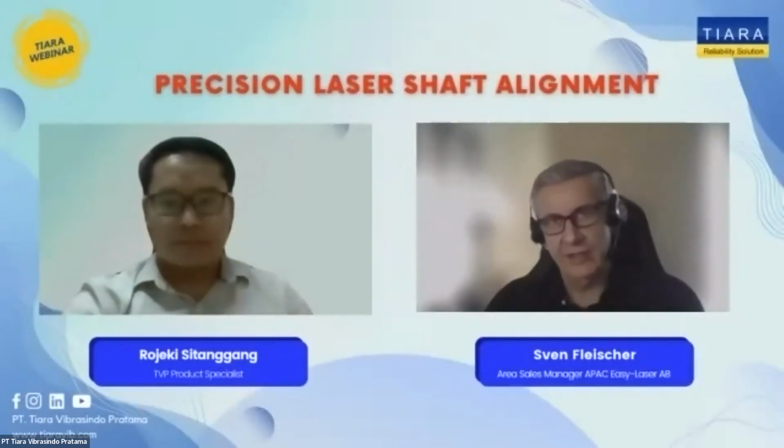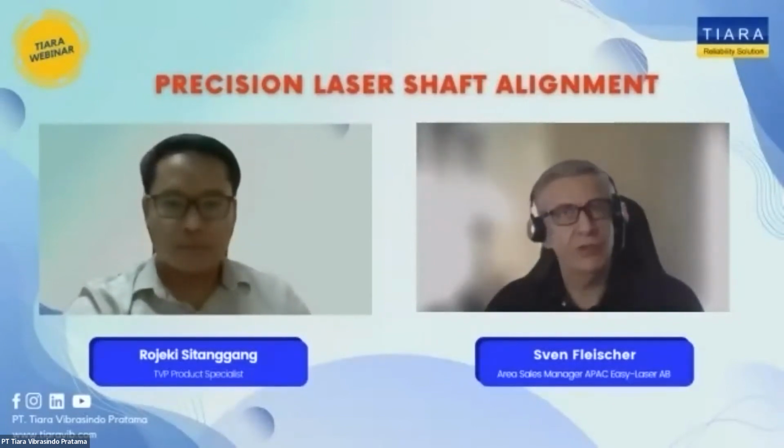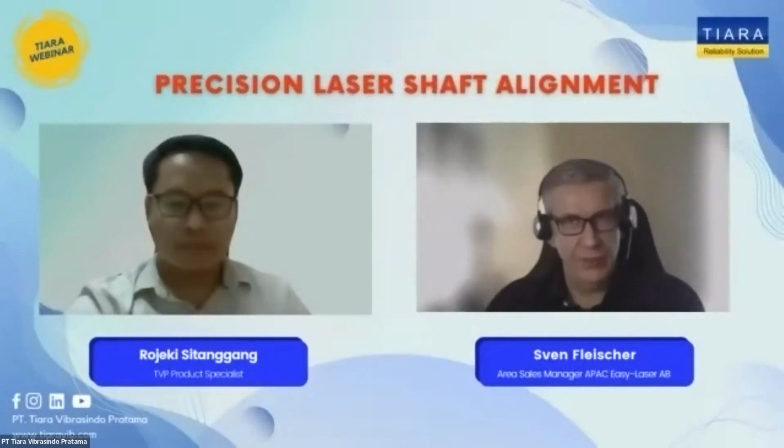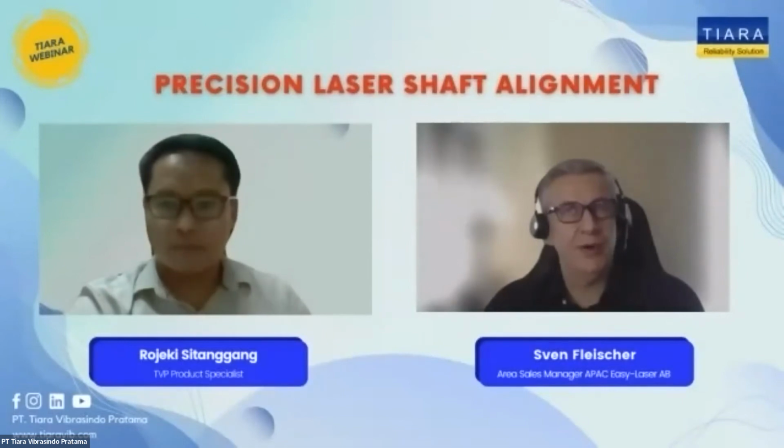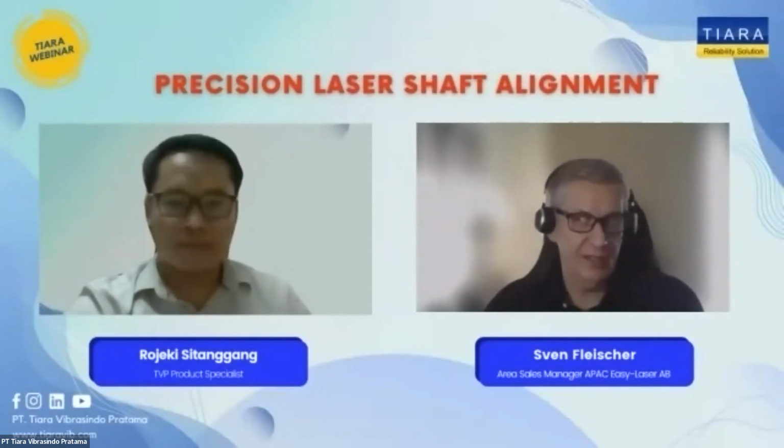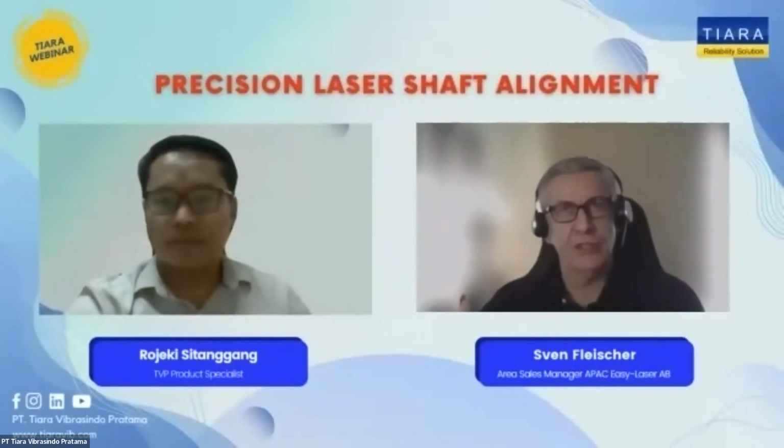Now, there's another consideration of how to measure, and I think the question relates a little bit to machines which are not possible to rotate so easily. We have a way called sweep mode or uncoupled sweep mode, where you can work with one shaft which is not rotatable.